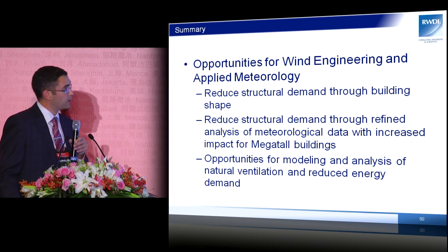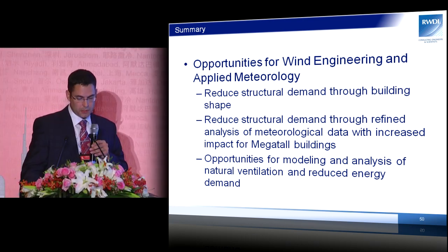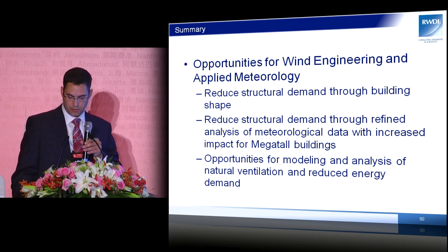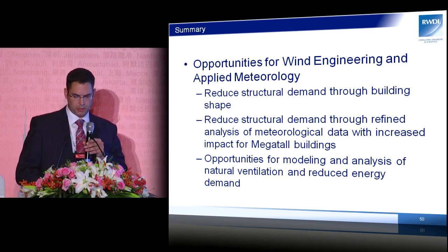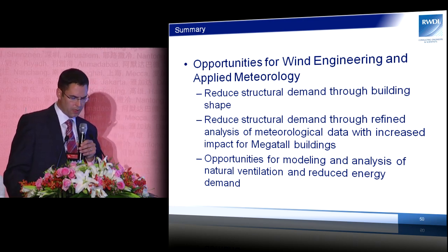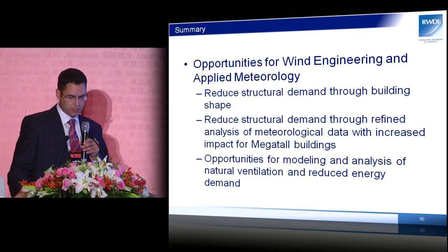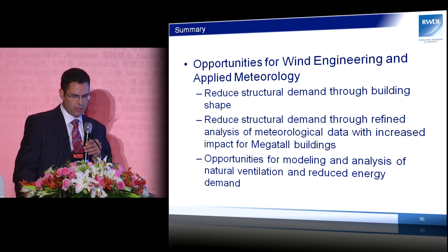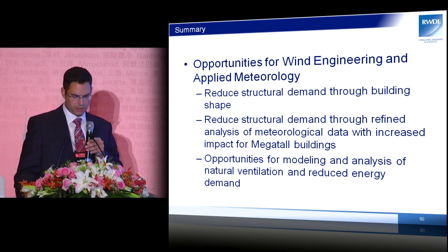And then just finally to conclude here, summarize a few things that I've talked about. Some opportunities for wind engineering that we can apply to projects, and we'll probably hear a little bit more throughout the session, and applied meteorology. One, we can certainly reduce the structural demand through building shape and considering the flow of wind in a positive way. Second, we can again reduce that structural demand through refined analysis of the meteorological data, and that certainly has a greater impact for some of the mega tall buildings that are being contemplated today.